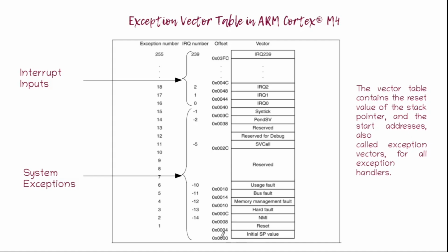I'm saying wherever because the address is not always 0000. This can vary. So this is already flashed onto the microcontroller prior to execution, of course, and then the exception vector table becomes a very important location from where it gathers a lot of information.